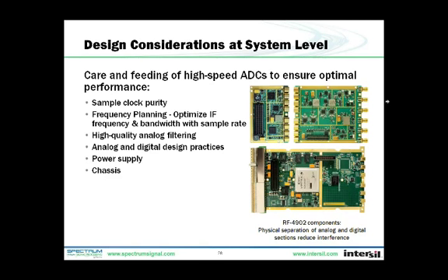These must all be considered together. So a higher sample rate isn't always better. You need to suit it to the signal of interest and then select where your aliases appear. In this case, the signal of interest is your IF frequency. You don't want those signals to overlap. Now, a fast ADC's ability to operate at a high sampling rate and operate with a wide range of sample rates helps you to do this.